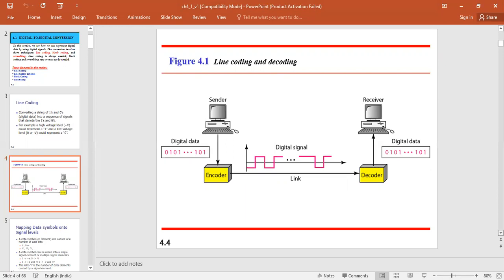Here we discuss what a data element and a signal element are. In data conversion, our goal is to send data elements, and the data element is the smallest entity that represents a piece of information. This is the bit. In digital communication, the signal element carries the data element. The signal element is the shortest unit of the digital signal. So data elements are what we have to send, and signal elements are what we can send.